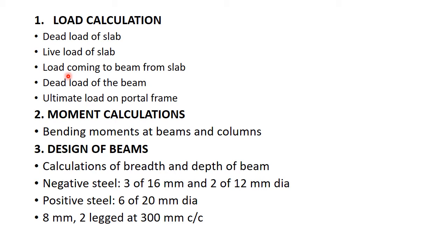You can use any one of the methods and you can calculate the bending moments as well as the shear force at the beams and columns. So once you calculate the bending moments and shear force at beams and columns, then we will go for the design of beams. That is your third step.